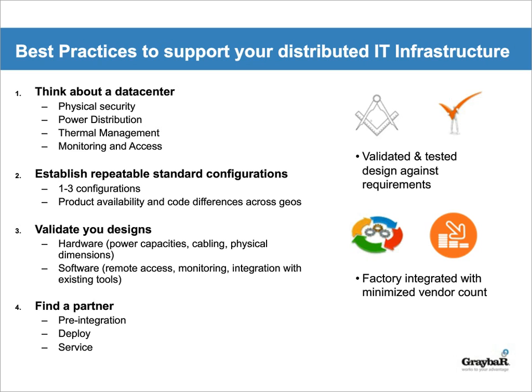Make sure your tools can monitor those UPS batteries, right? So you don't have the problem that so many people have with their batteries being outdated. Make sure your monitoring tool will read the temperature sensors in that rack PDU, let's say, or that temperature sensor that you put in that location. And make sure you're getting those alerts, right? Test this all and make that software configuration part of your repeatable standard configuration.